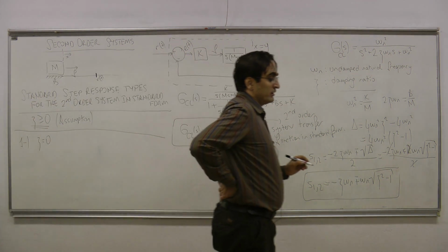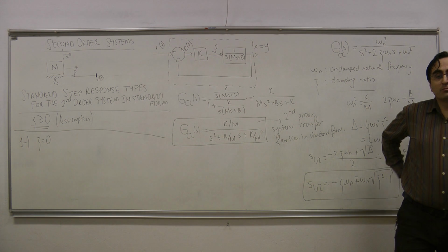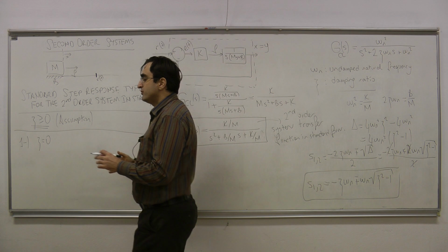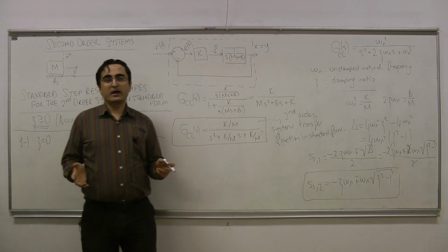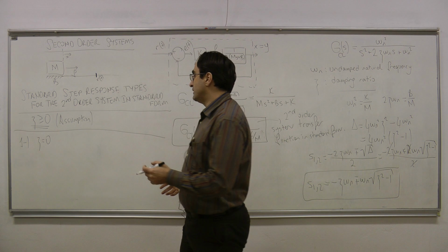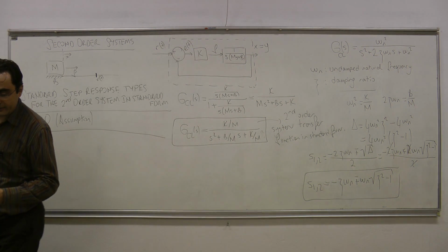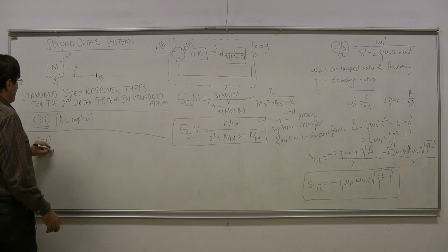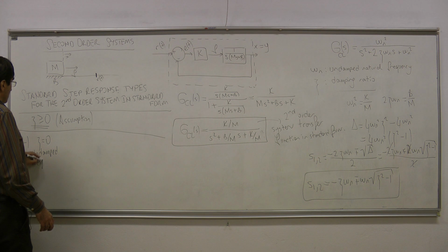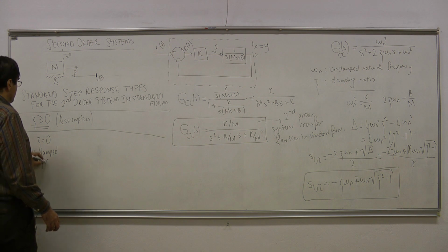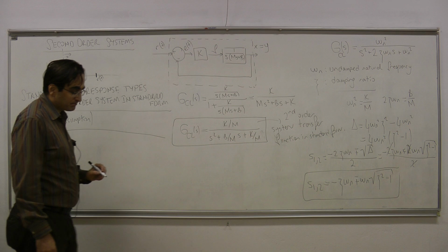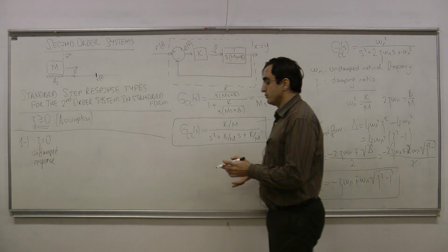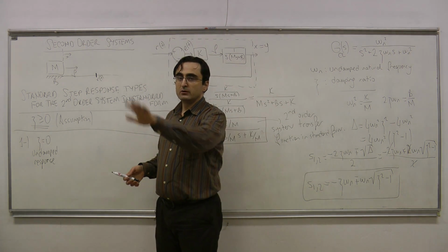When the damping ratio is 0, that is going to mean that there is no damping in the system, which means that the oscillations are no longer going to decay. Therefore, the name of this case is actually the undamped case. In this case, we also call it the undamped response. Okay? So in this case, there is no damping in the oscillation, so they will continue forever.